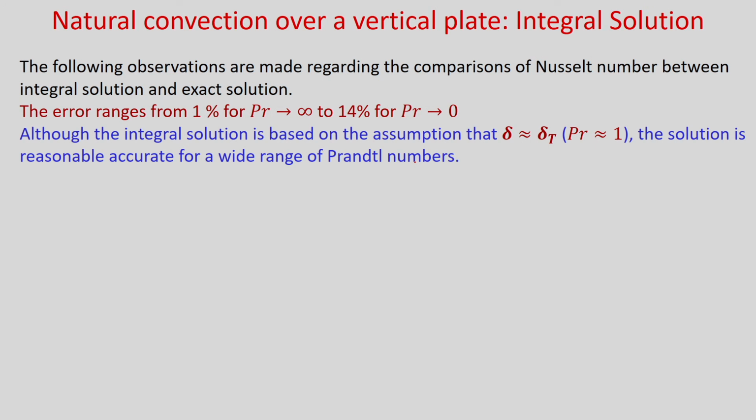So, in today's class we have solved the boundary layer equations using the integral method. First we integrated the momentum equation and the energy equation, and we have written the momentum integral equation and energy integral equation. Then we have assumed the velocity profile and temperature profile, and invoking those expressions in the integral equations, we have written two ordinary differential equations.